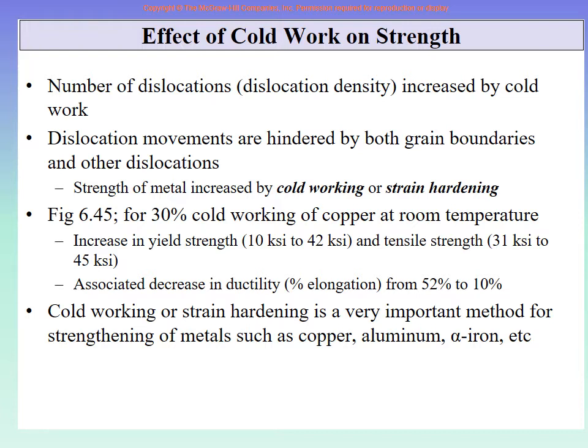So this is the same thing as we are saying here, the effect of cold work on strength. Cold means we do it at room temperature. If we do the same thing at a higher temperature, then this will not happen. But if we do this at room temperature, that we load it until it reaches the plastic region anywhere, then offload it, then load it again, then we have increased the strength. So why does this happen?